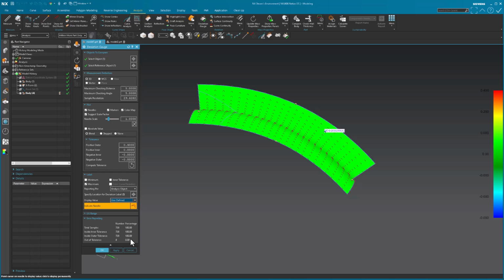And I can translate those points from one CAD system to the next. I can write them down manually and enter them in manually. I could do whatever I want to, and as long as the CAD system or the CNC system is NURBS based and does things with standard NURBS modeling math, which most of them do, you will always 100% end up with the identical surface, always. Okay, never say always, never say ever, blah, blah, blah. In this case, always. Because the control point, math is math. It'll never be anything different, ever.